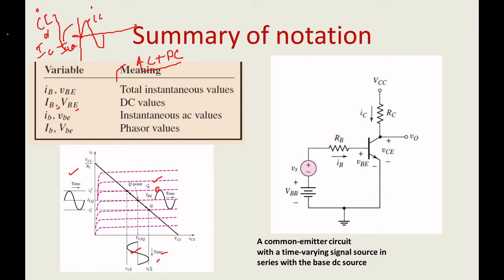Okay, here you can see you have a source signal, and your battery 1 is biasing the base terminal. IB is the current across your RB resistor, and VB is the drop across your junction 1, and this is your J2, and this is your output port with the voltage drop of VC, and RC is your output resistor.